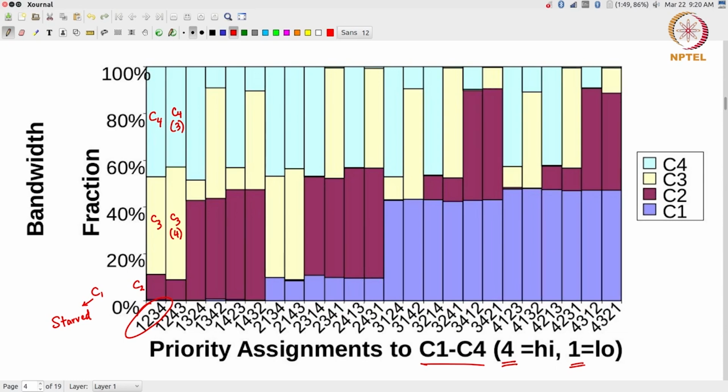That's when you have 4. Okay, if you have more of them, the situation will be somewhat similar. At least you would definitely have some that are starving and some that are hogging all the bandwidth. Okay? So in other words, static priority assignment has this problem, right, that if all the masters on a heavily loaded bus, in other words, that is when all the masters are trying to generate large amounts of data, there is a very severe problem of unfairness.